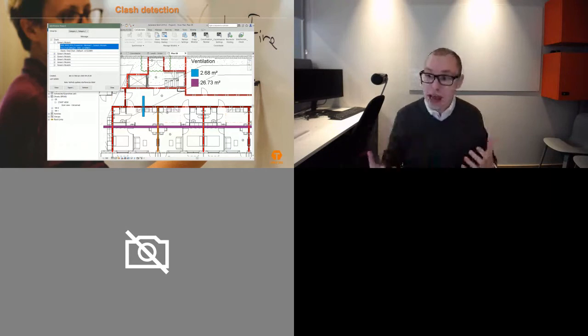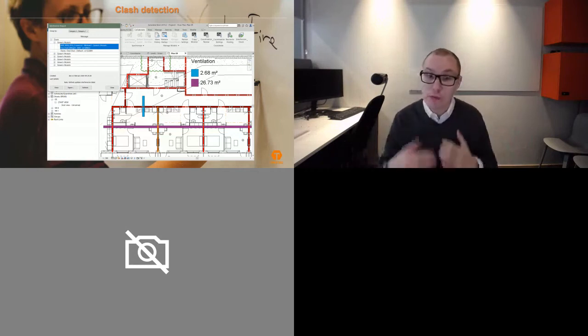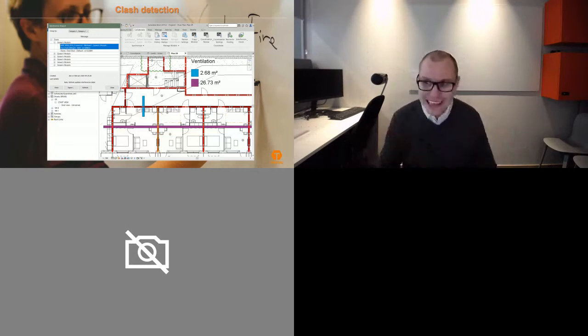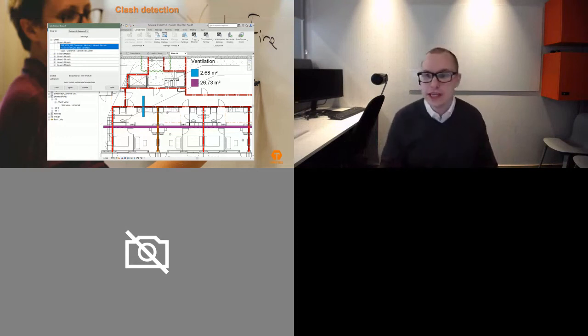do checks: have we put in dampers in all the penetrations or close to those penetrations? What kind of material are we using on those pipes? Do we have plastic pipes going through this compartmentation? This can be easily found just by having a 3D model as a fire safety engineer. So those are the kind of indirect values that we get just from having a model.